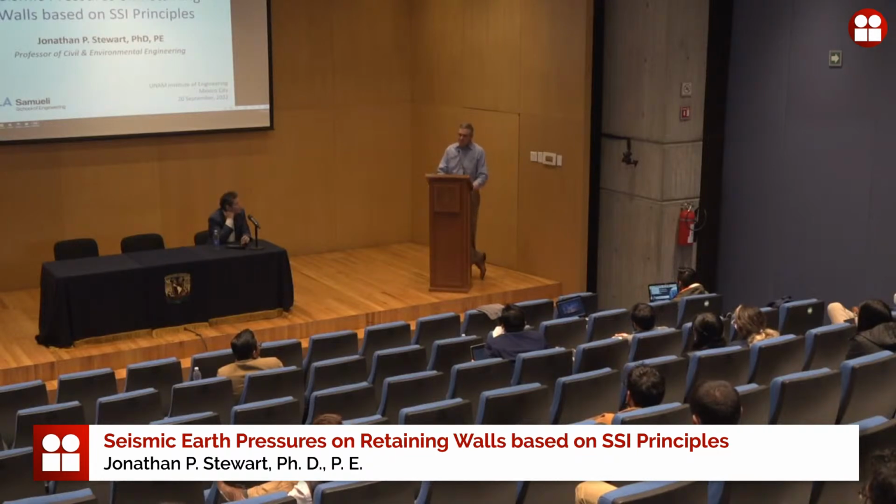Okay, so are there other things that I haven't told you, basically? Yeah, I mean, in the course of doing work like this, there are all kinds of things you try before you settle on what you think the key factors are. So one of the things we looked at in considerable detail, we thought it would matter a lot, was the non-uniform soil. We spent a lot of time on the flexibility and shear and moments of the foundation of the wall, which is really important for a rigid wall. It turns out it's not that important once everything becomes flexible.